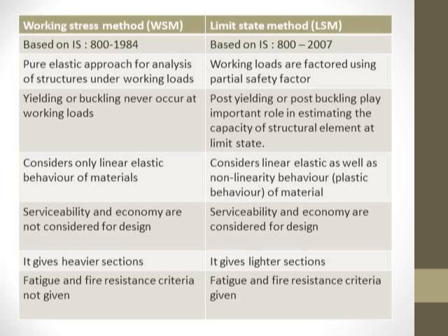One more difference is that heavier sections are used for the working stress method, whereas lighter sections are used for the limit state method. Also, fatigue and fire resistance criteria are not given for the working stress method, whereas fatigue and fire resistance criteria are given for the limit state method.